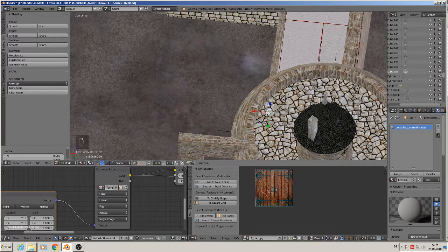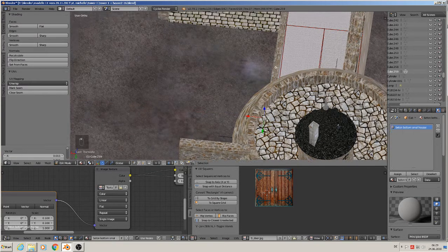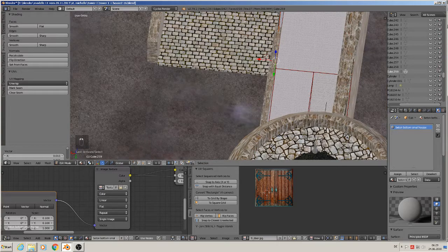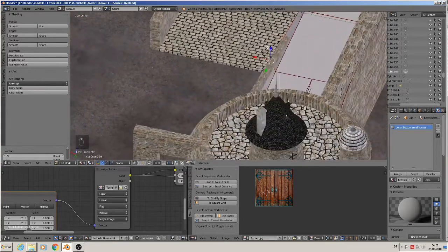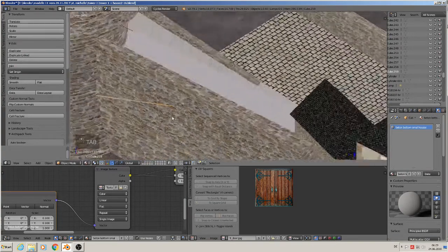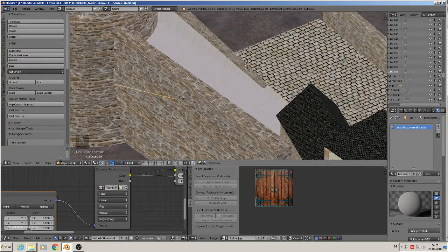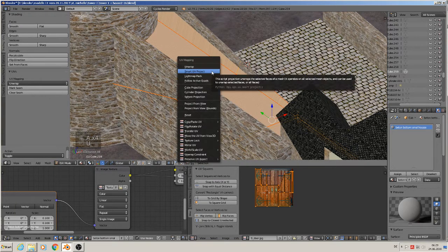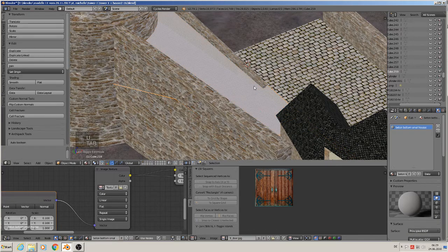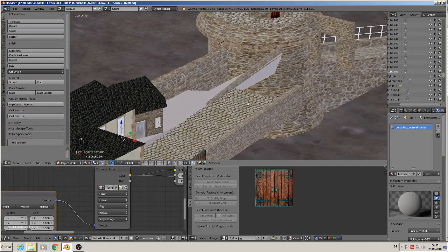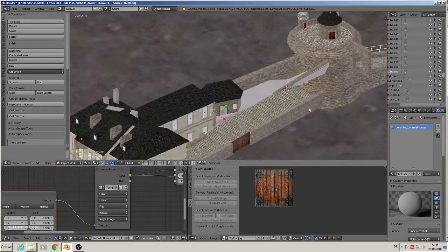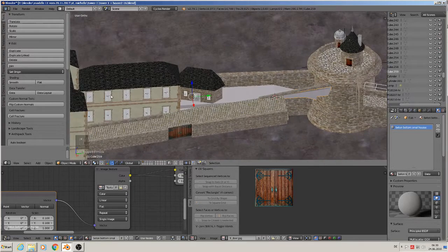Oh, that wasn't that. Yeah. But here too. Okay. Good. We have to make it again here. So object, apply rotation scale, and unwrap Smart UV project, ready to go. Good. That is closed. Here comes the road and makes a curve. That is the next step to do.